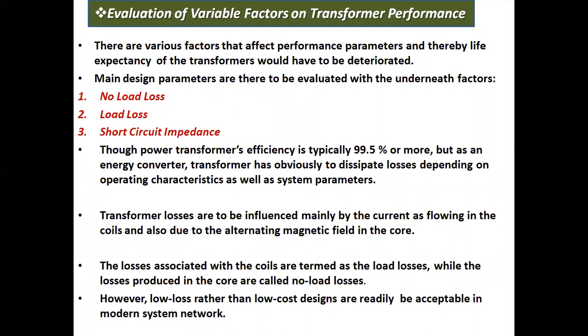Evaluation of variable factors on transformer performance. There are various factors that affect performance parameters, and thereby the life expectancy of the transformers would deteriorate. Main design parameters are to be evaluated with the underneath factors. 1, no load loss, short circuit impedance.